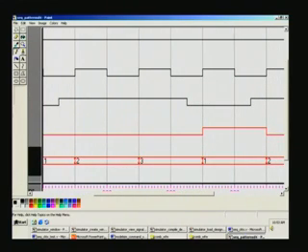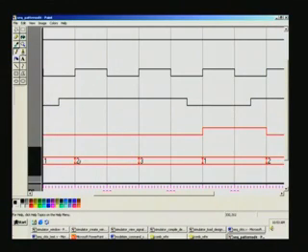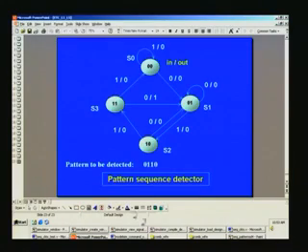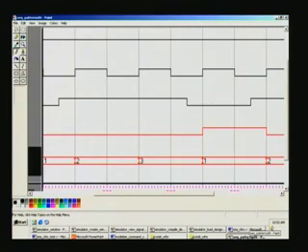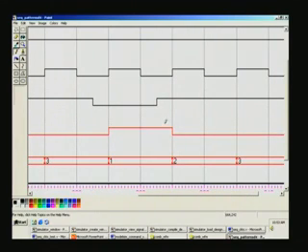In S2, if it is 1, you go to 3, you are in S2. So, this is 1, right, is it correct, 2 to 3, and next from 3 you have to go to 1 provided it is 0, state 3 and input 0. In state 3 input is 0, right. So, it should go to S1, is it going there? Yes, right. In state S1 this only produces that 1 again, right.